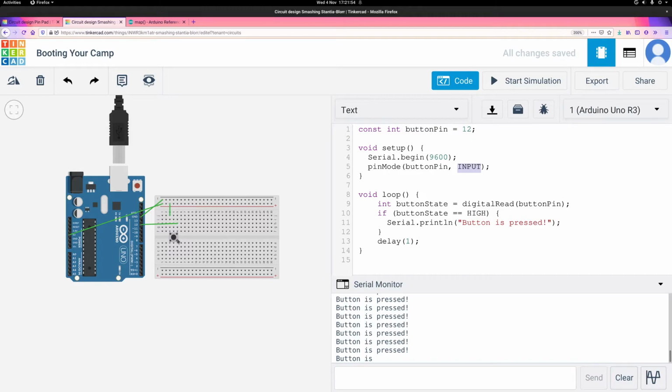But it's a bunch of this little interference and noise, which is not what you're looking for. So, as Jacob has mentioned, what we can do to solve this problem is add what's called either a pull down or a pull up resistor. And those differ just in the direction that they're kind of connected. I'll show you a pull down first. So that's the external component one.